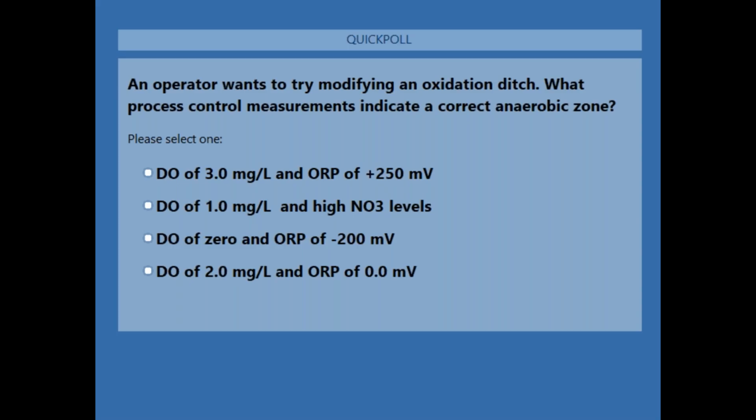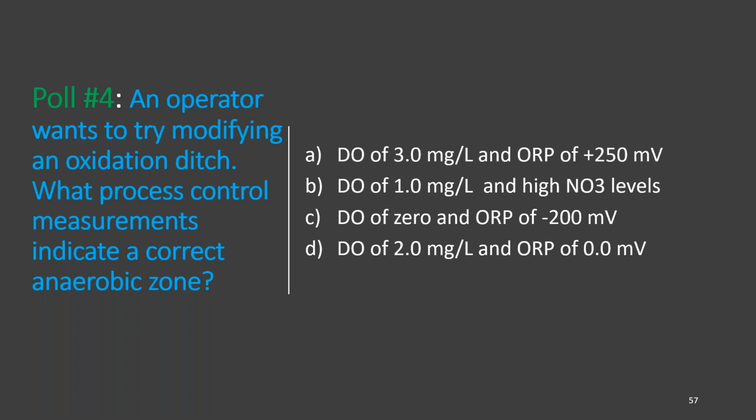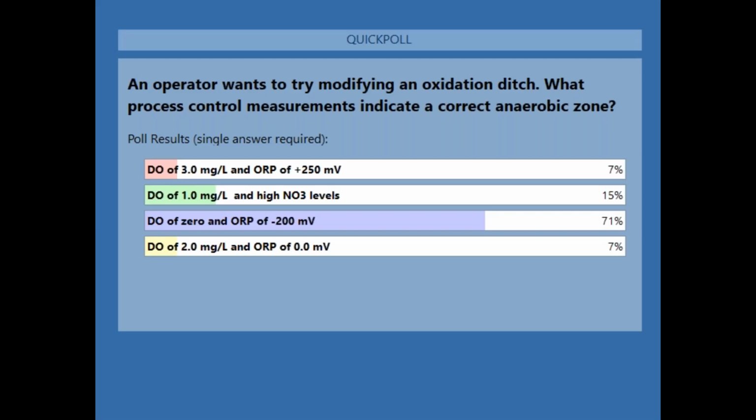So there's a feeding frenzy going on near the front of the oxidation ditch, and the amount of ammonia oxidation that's occurring is a lot smaller until we get to the end where the BOD is removed. So there's not a clear distinction. It just can't really begin working efficiently until near the end.